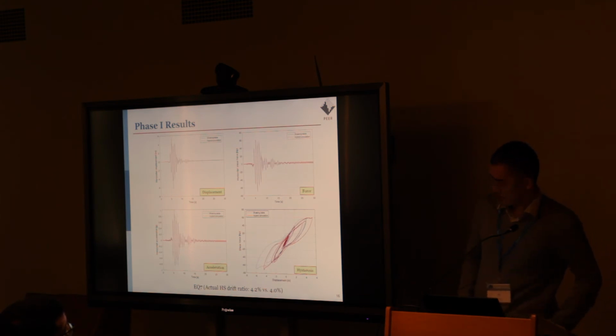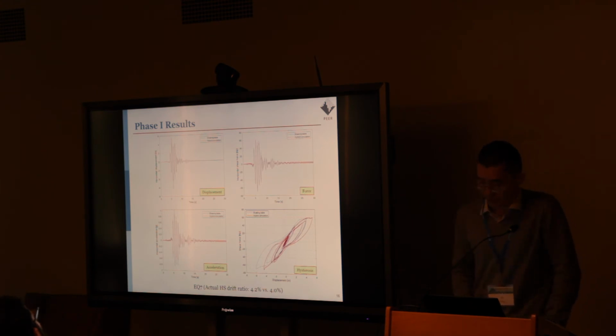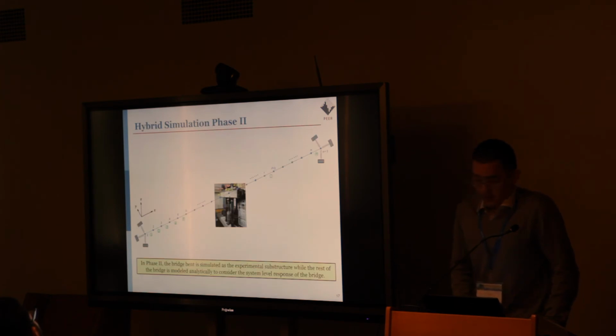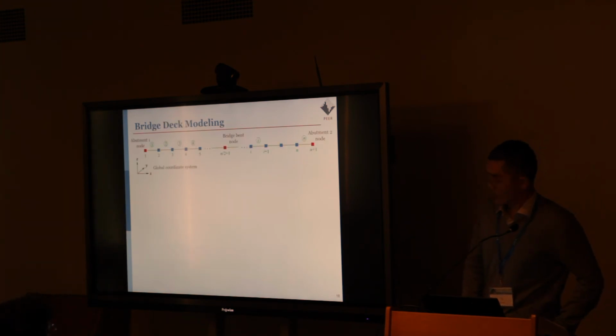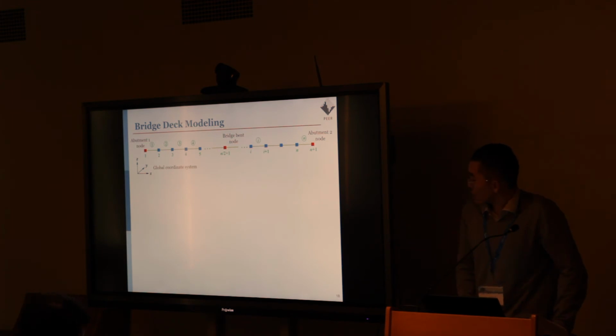And this comparison and verification will increase our confidence in the application of hybrid simulation in the structural engineering community. And in the second phase, the bridge bent is simulated as the experimental substructure, and we incorporate the full bridge to study the system level performance of the bridge. So in terms of the bridge deck modeling, the top figure shows the subdivision of